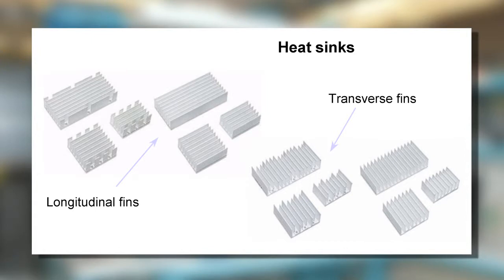Once the thermal parameters of the design have been calculated, that means the temperature increase and the power dissipation, and once the surrounding conditions are known in terms of, for example, airflow and ambient temperature, it is possible to choose the proper heatsink, either from the assortment that Vicor offers in terms of accessories or from third-party manufacturers, which offer a broad range of different shapes and sizes of heatsinks that could accommodate any kind of application.